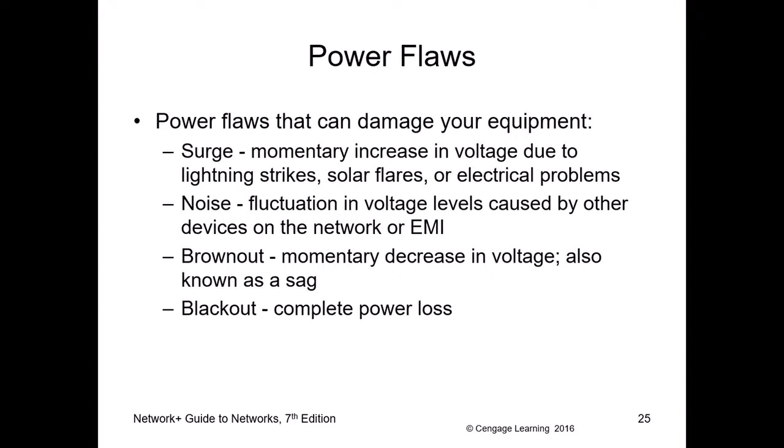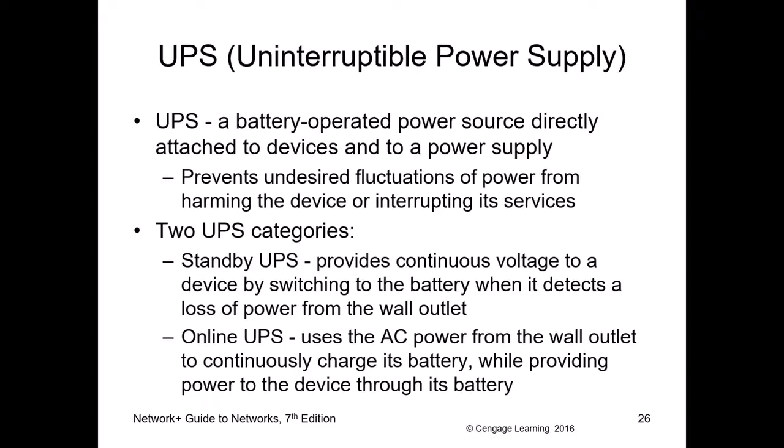So what do you do then? You need a UPS, an uninterruptible power supply, right? To take care of surge or noise or burnout, you buy those voltage suppressors, right? That you put in so you don't ever connect your electronic devices, your laptops, your servers or your switches directly to the wall outlet.